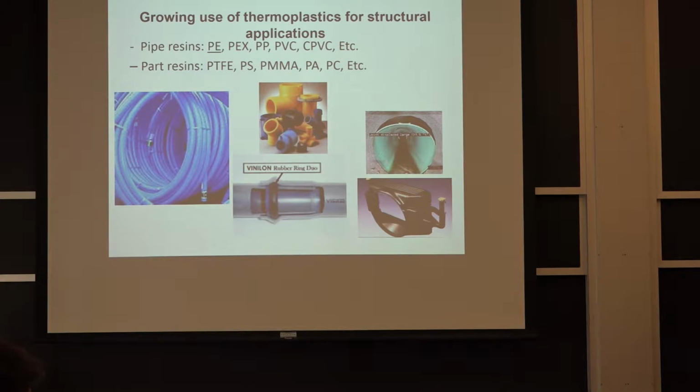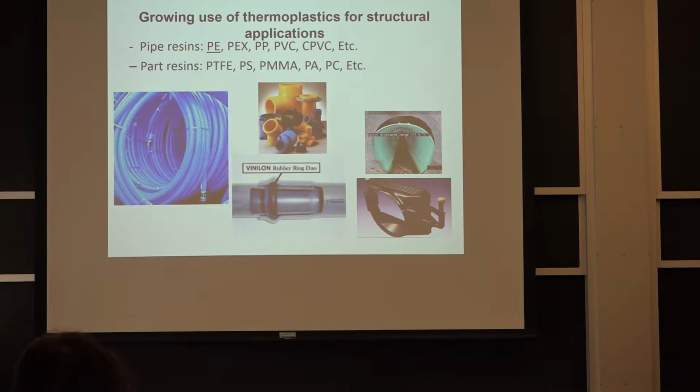There are a lot of applications for plastic, even if we're thinking very demanding application. One thing we discussed last week is the creep limitations, but despite having to deal with creep, you have a lot of unreinforced plastics used for very demanding application, including natural gas distribution, especially in the Boston area. You probably hear or smell natural gas every once in a while. So a lot of the old pipes are leaking. And for distribution, it's since the 1980s, approximately, that people have more or less stopped using metal pipes, mostly for the issues with protecting against corrosion.